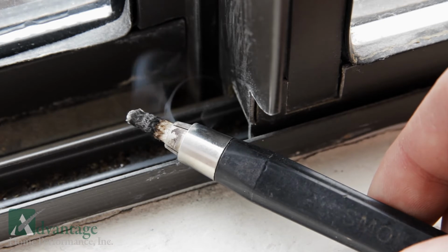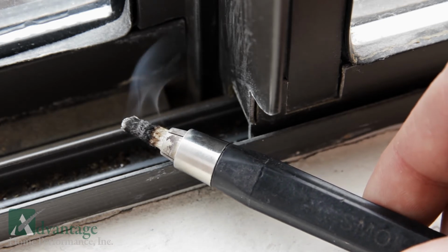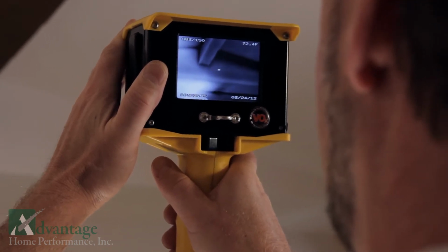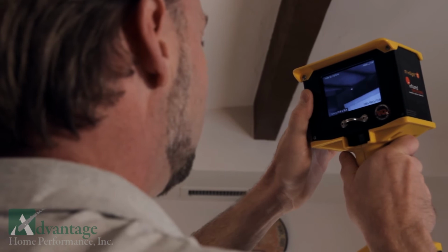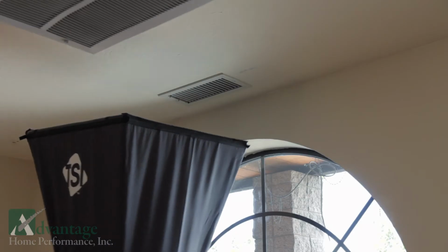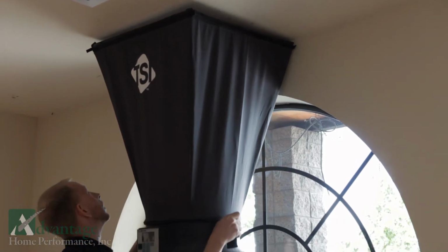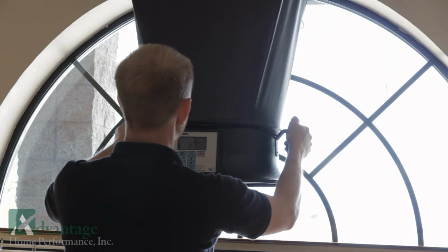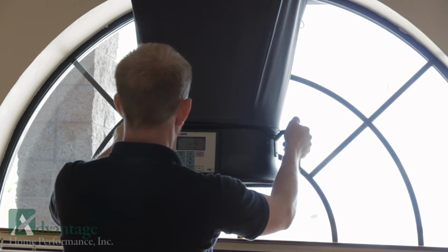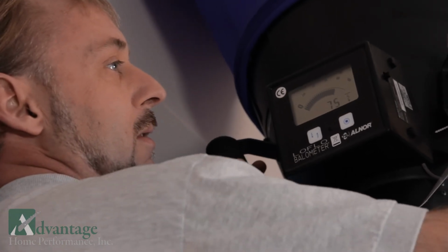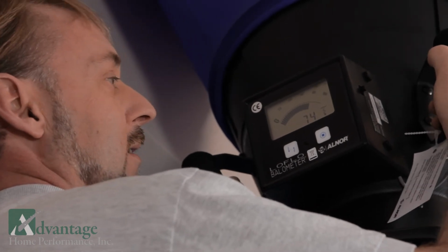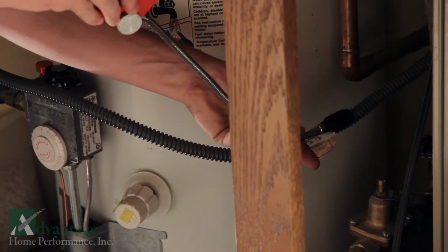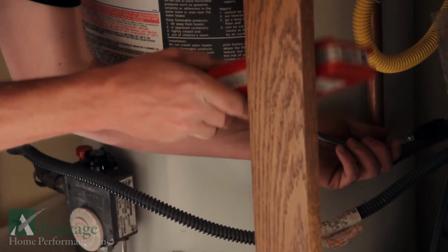Most homeowners are surprised to learn that the doors and windows are not the biggest source of air leakage. We use an infrared camera to locate missing insulation. The infrared camera can see temperature differences down to 1/10 of a degree. To solve problems in uncomfortable rooms, we use a flow hood to measure if the room is getting the proper amount of airflow to satisfy the room's cooling or heating needs. Although this is not a utility audit program requirement, this tool provides us valuable diagnostic information. For health and safety purposes, we perform testing on all combustion appliances and check for gas leaks.